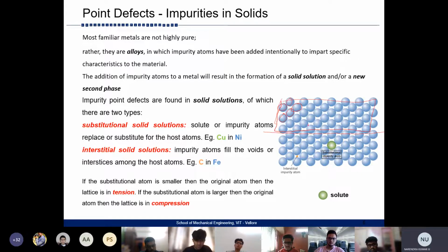So what types of impurities can we have? We can have other atoms of a similar size to this atom, and they can take the lattice point, or you can have another solute atom which is much smaller in size, and it may take the interstitial site. Whatever other solute atom comes inside, they are nothing but the impurities of the system. So two possible ways are there. There can be larger atoms, and much smaller atoms which sit in the interstitial.